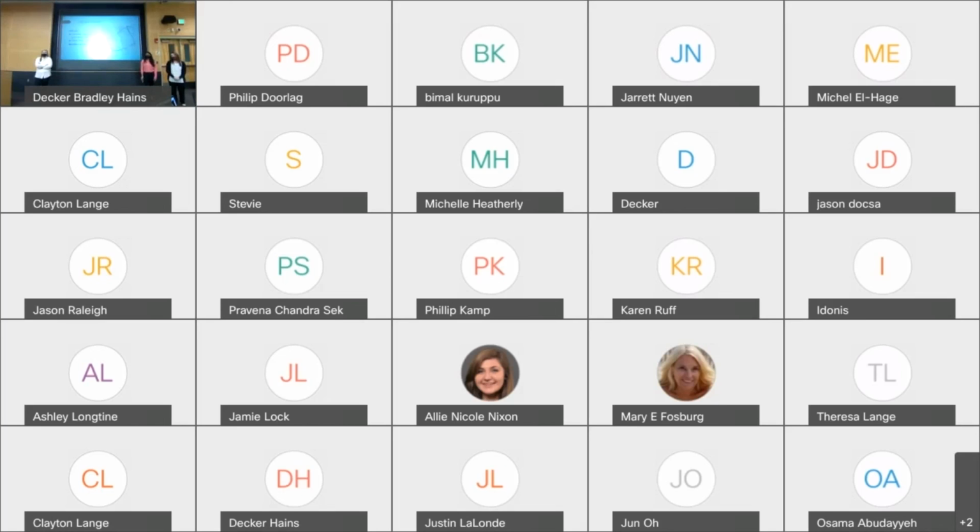So what would be the new level of service on the detour route? With the split route, once you send traffic to the detour route, what would be the new level of service on that detour route? Did you look at that? So the level of service that's shown in this table is with the new traffic. So we did not go into the analysis of splitting it, we just chose the best one. We have a disclaimer in our report saying that we realize traffic counts for year 2020 are really low because everyone was working from home. So we decided that 2 routes would be able to help if the level of service with the accurate, pre-pandemic numbers makes a route fail. So we can then split the traffic in half and represent 2 different routes.